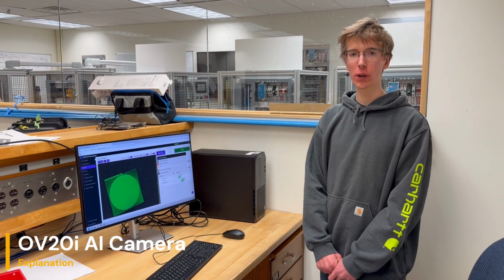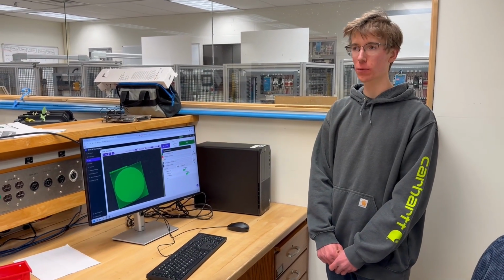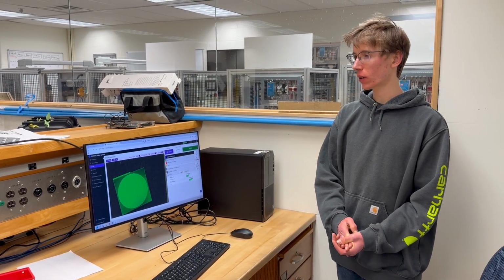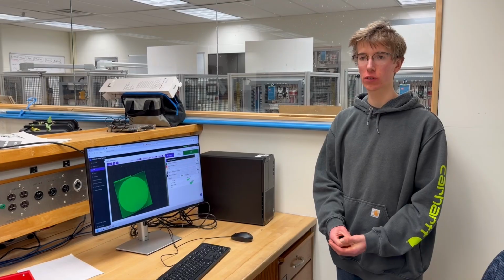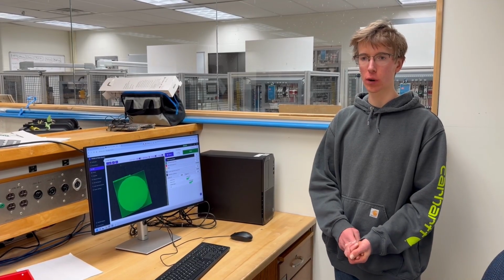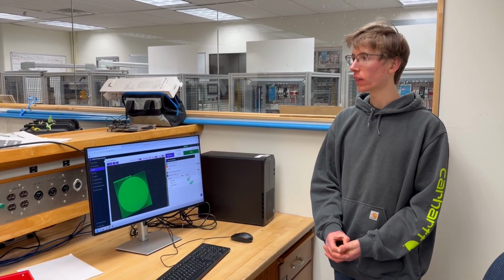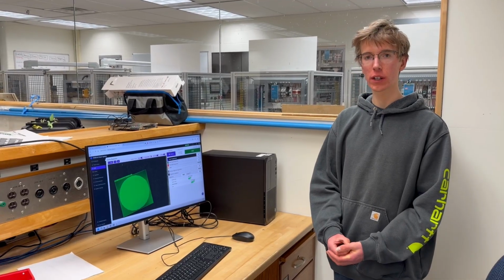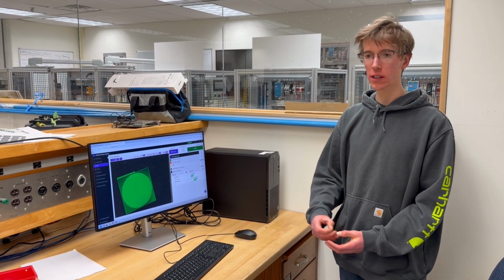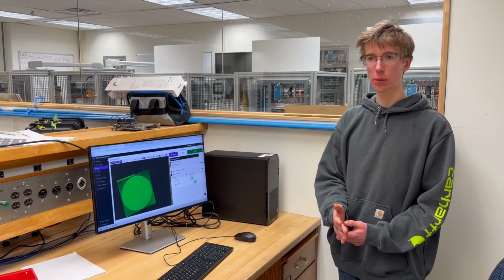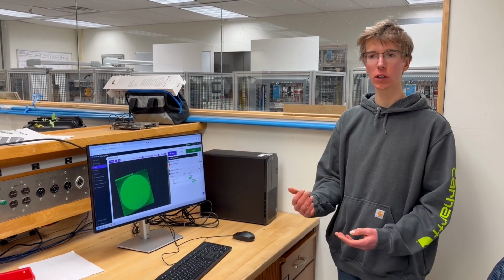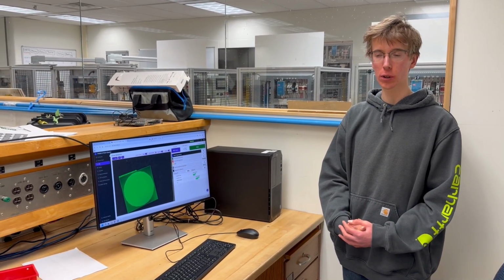We trained 3 different part evaluation models, one for each of the shapes we were detecting: circles, squares, and triangles. The evaluation models are detecting the print quality or any scratches or burrs that would be harmful later down in the process. The camera interfaces with the PLC through an Ethernet cord. The PLC sends image capture requests to the camera, and the camera sends back pass or fail, along with multiple different status bits that we use in the program.